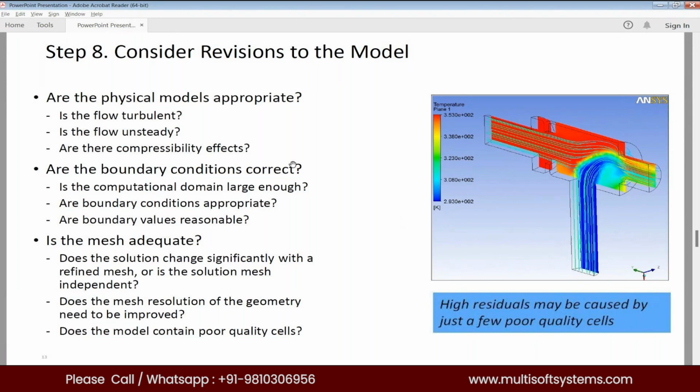In that case, we can go back to what the actual physics is in that particular computational domain. We can understand this from very basic, fundamental books and research papers in that area. We can also take similar references from numerical analysis research papers. From that we can understand if we are missing something on the modeling side. Then about the boundary conditions, what type of data we are getting from the field, and whether the same has been applied in the numerical models, the boundary condition types, their values and their reasonability. Those aspects can be checked.